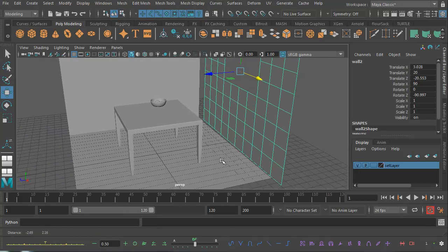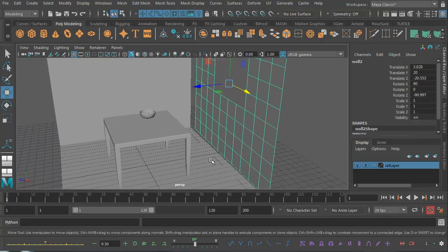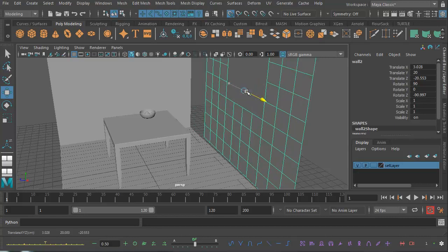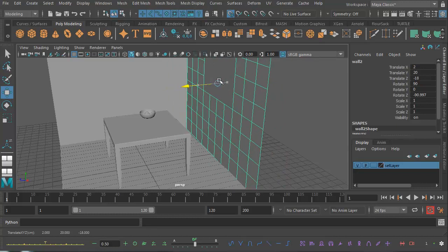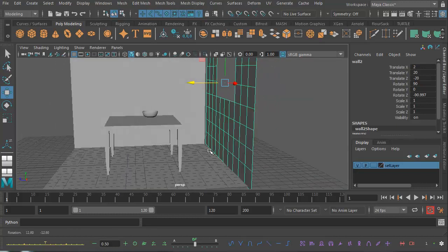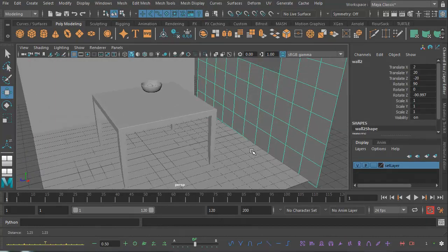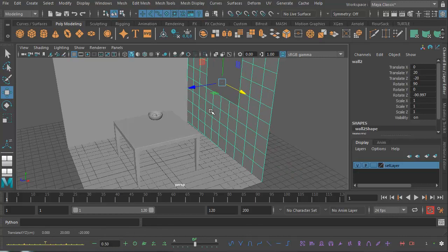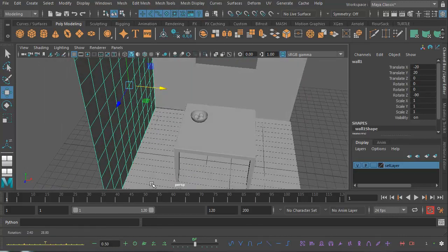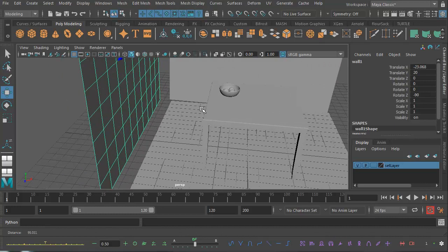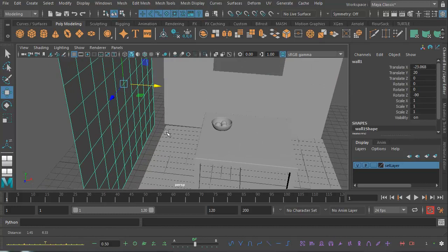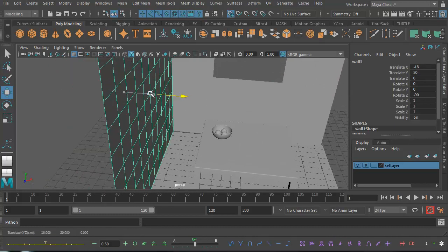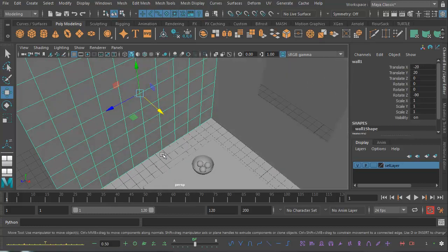So what we do is we grid snap it. We snap it to the grid. And to do that, you hold down the X key and then manipulate these controls here. So what I can do is line this up holding down the X key so that it snaps to the grid like that. And I can do the same thing with this one here. If I move that out of the way for some reason, I can hold down the X key and snap it back into place.